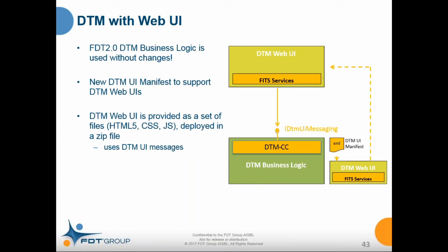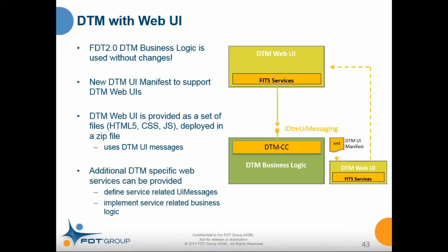Now, if this user interface is hosted in a browser, it can use the already existing and defined DTM user interface messages, so it is possible to use these messages. You could also define your own or additional DTM UI messages in the business logic in order to support some new user interface, but it's important that this does not need any new FDT interface.